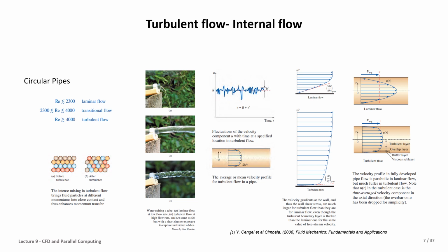But when we have the turbulent regime, they don't have a uniform structure, they don't move in lines, and they mix together here. This is a presentation of the flow in the pipe, which is internal flow, and we can see from up to down how laminar, transition, and turbulent flow have different presentations.